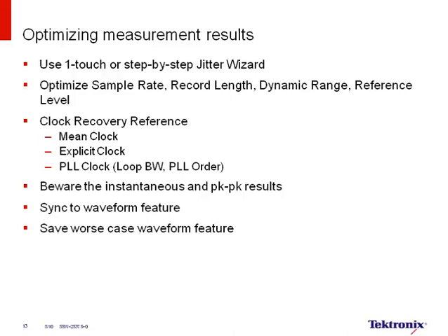Another way to do that is to use values like TJ and RJ. Again, those techniques, these dual-Dirac results, for example, have these statistics embedded into the results. So the TJ actually has standard deviation information already embedded. So that's another technique to be able to document your jitter analysis results.